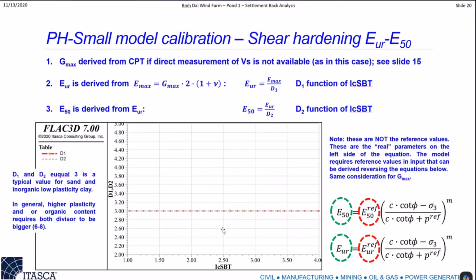I have applied this methodology for decades, with very good success, even in the design phase, when you don't know what is going to be the performance. But applying this strategy gives you a very good connection with the soil distribution and the expectation of these properties on the site. And then when you get to the end of construction, you have the monitoring system that provides you some feedback. I've seen decent, in some cases remarkable, results, but all in all, let's say within a maximum of plus or minus 20% in terms of settlement, and in some cases very, very close.